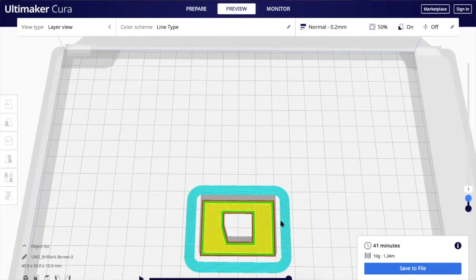It makes, first of all, the base. So everything here is full. The red lines are the outer part, and the blue lines are how the printer starts. So it starts from the outside. This is not part of your design, but it's just for making the plastic flow in the nozzle a little bit, so for purging the nozzle.